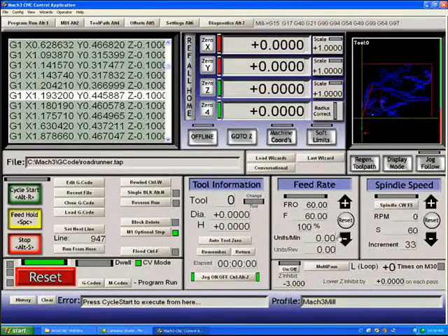We have a feed rate selector. This is feed rate override. We have units per minute and units per rev that are real-time updates as you're moving. Here we have our spindle speed selection. We can turn a spindle on or off. We have spindle speed override, that we can override the spindle speed that was set in the GCode program and allow the spindle to speed up or slow down. Pressing reset will of course bring it back to 0.